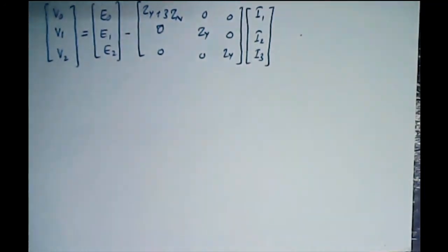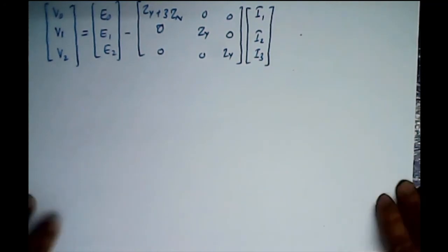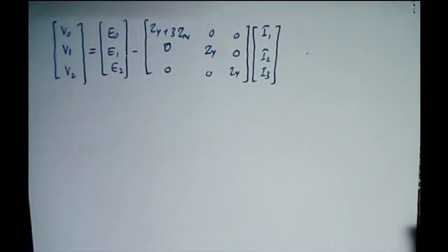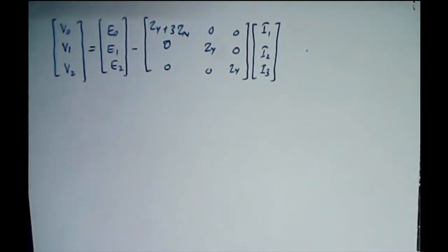Now one more thing, when we are talking about the generator, the phase sequence is always positive. The direction of rotation will be the reference, right? The angular separation is always the same because it is fixed at the time the generator is designed. And if the magnetic field weakens, then all the phases, phase A, phase B and phase C, will be affected accordingly.